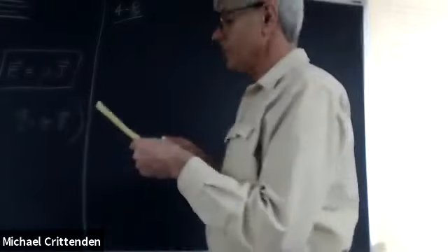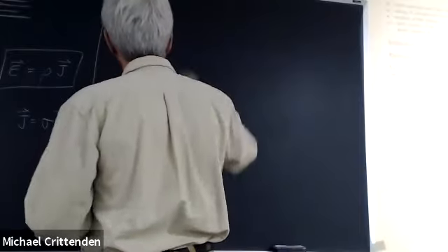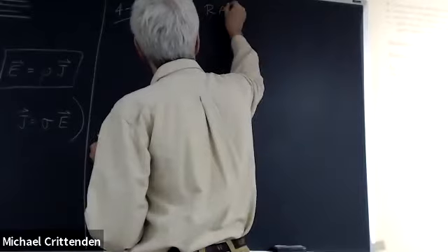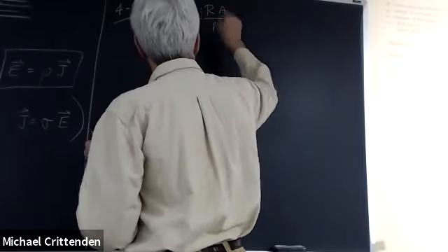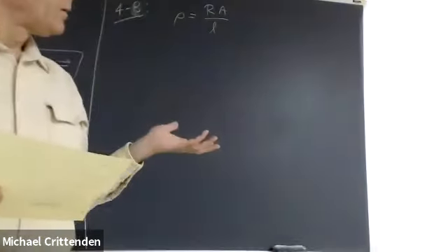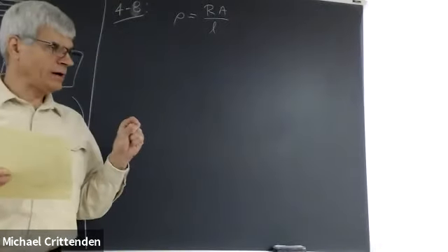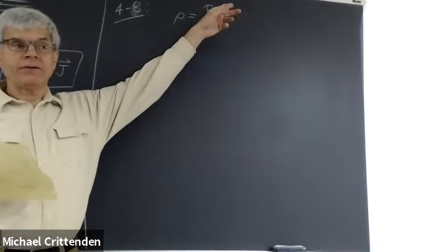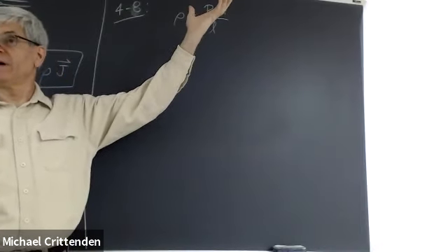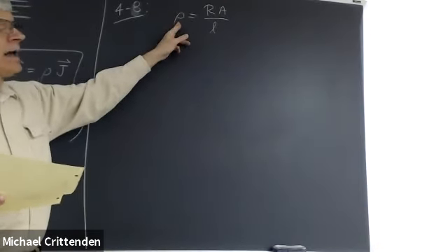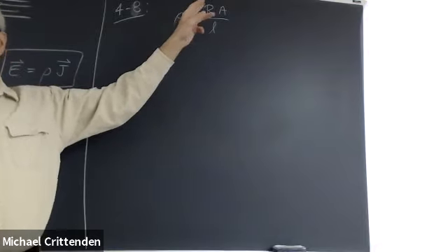As it says over toward the left, resistivity equals R times A over the length of the wire, which in this case is 2 meters. So the question is, what's the diameter of the wire? Well, if I know the area, that's just a short step from knowing the diameter. Area is pi r squared, and then you double the radius. I can look up the resistivity of nichrome.